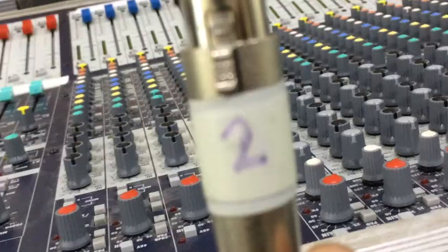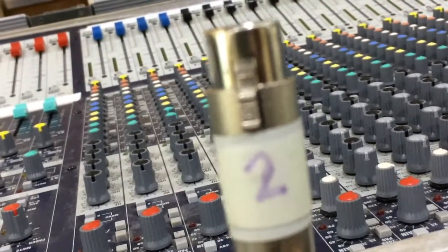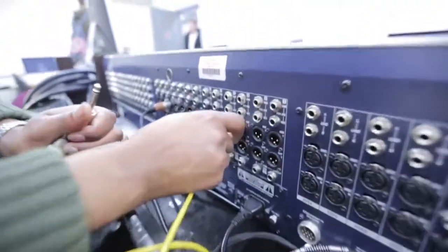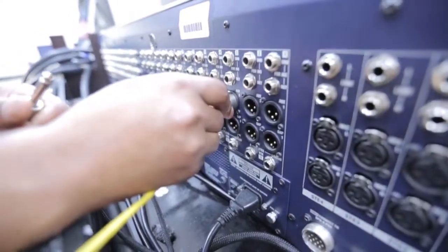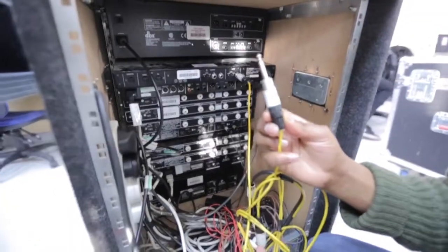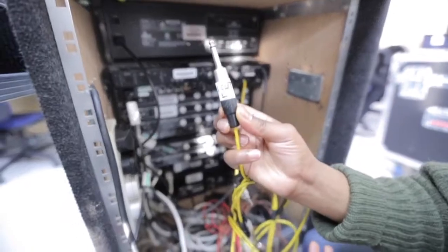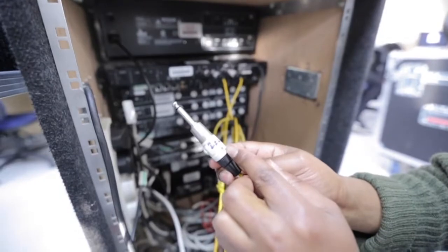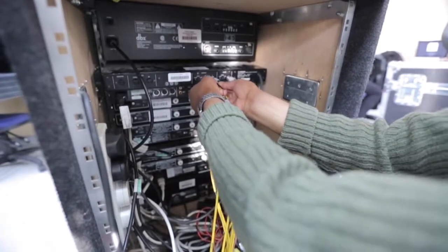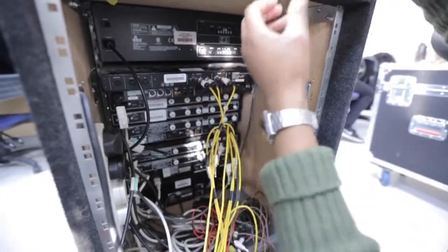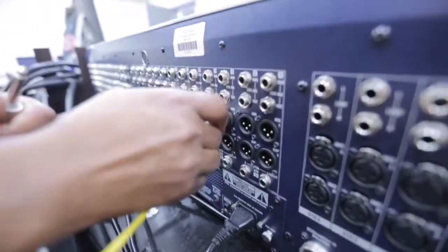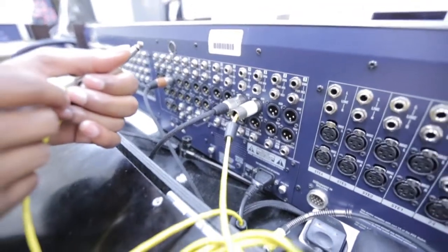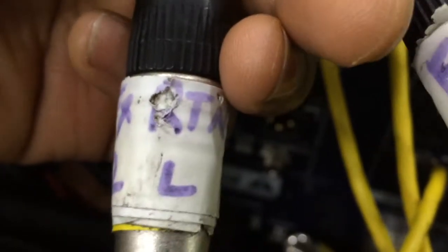To send the signal to the reverb unit, I'm using the XLR output auxiliary 3. I'm plugging the XLR connector labeled 2 into the socket labeled 3 on the back of the unit, and I'll take the jack connector at the end of the cable labeled 2 in and plug it into the left input at the back of the reverb unit. To send the wet reverb, I would use the jack connectors labeled 2 out left and 2 out right. These are connected into the left and right outputs at the back of the reverb unit.